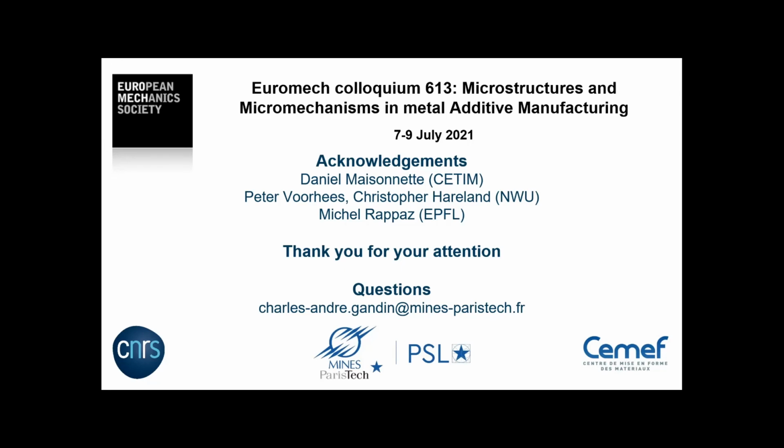So we have absorptivity for the various parts: the dense material, powder and liquid, and of course all this then needs to be adjusted. So we have comparison of remelted shape, depth, width. And this is in the publication that I mentioned. So this can be adjusted.